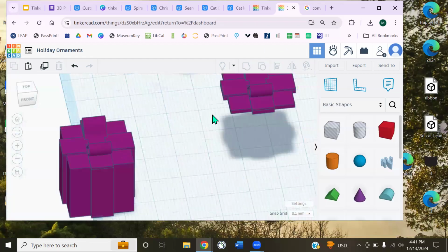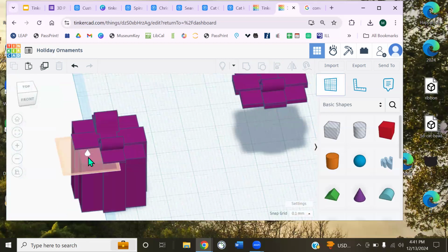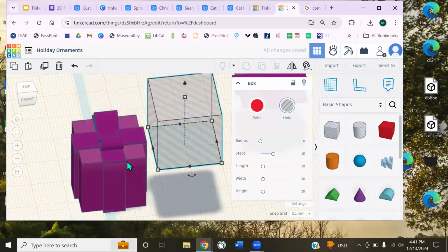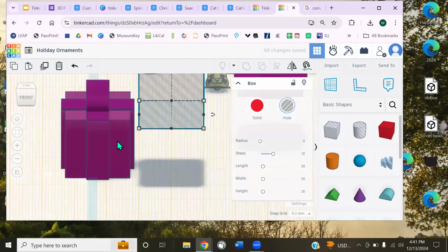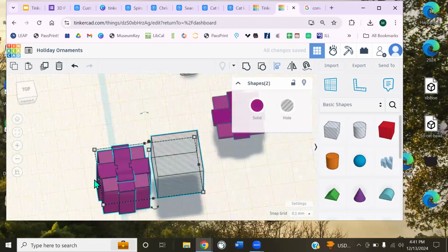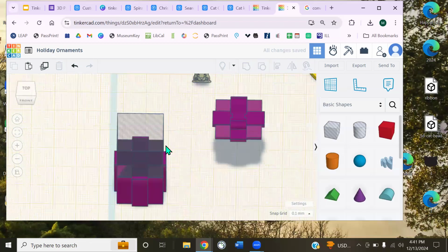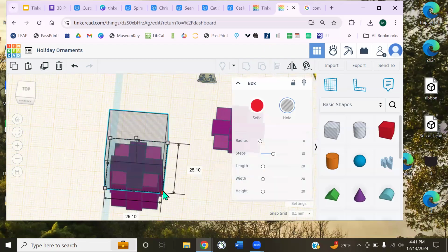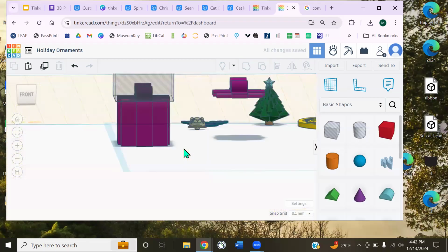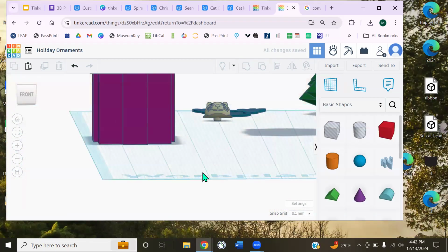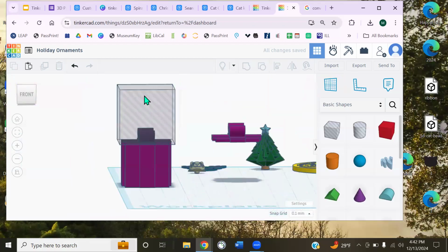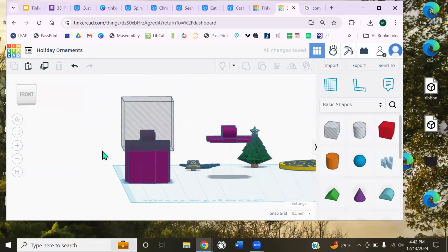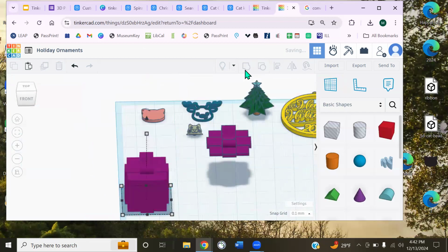And then we'll do the same thing with this. I'm going to put my plane tool on the top edge of the box. I'll put this cube flush with it. Going to come in, align them so it's in the middle. Let's expand the box because it's missing the edges actually. Like that. Yep, and then we just want the base of the box itself. So I'll click on my hollow tool, and I can just move it down like that. And then I'll go ahead and group that.